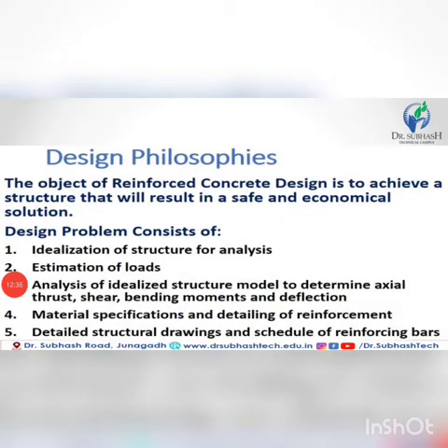Third, analysis of idealized structure model to determine axial thrust, shear, bending moment, and deflection. Fourth, material specification and detailing of reinforcement. Fifth, detailed structure drawing and schedule of reinforcement bar.